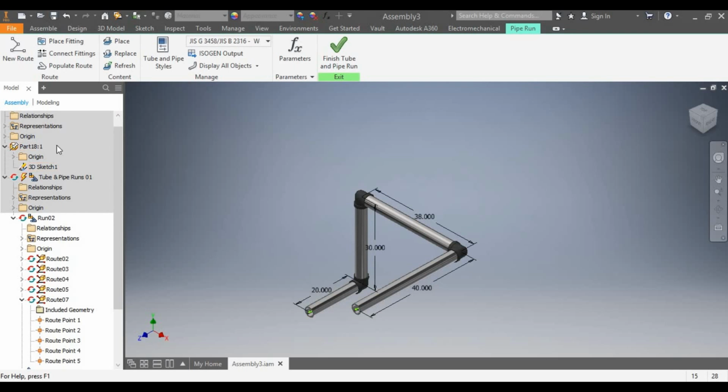One thing has been unclear: you can create the part in assembly, or you can create the sketch in a separate IPT file and then open it in assembly, and then you can perform pipe routing with the IPT sketch file. Thanks.